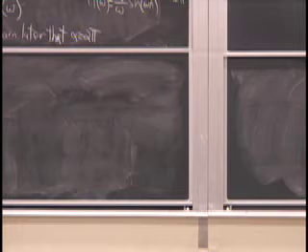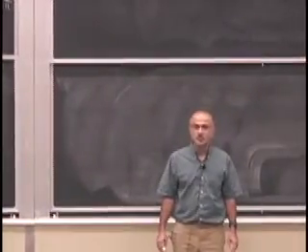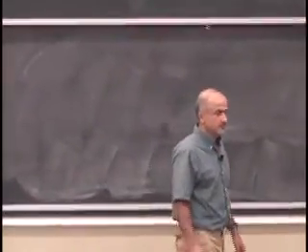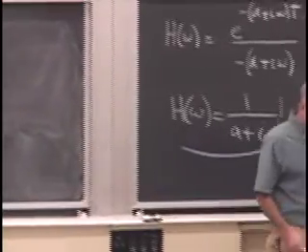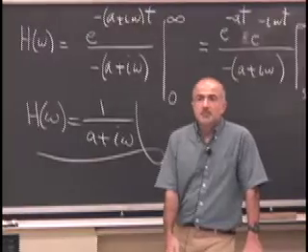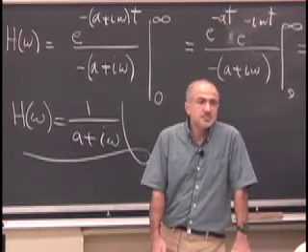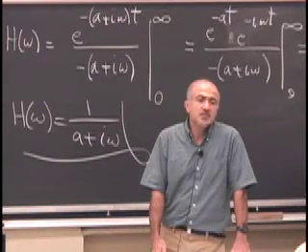This won't have a difference equation representation. Very good question. So this is an example of an LTI system that cannot be represented with a difference equation. No, it doesn't have to be infinite duration. The guideline is that you typically need impulse responses that can be represented as a linear combination of one-sided exponentials.